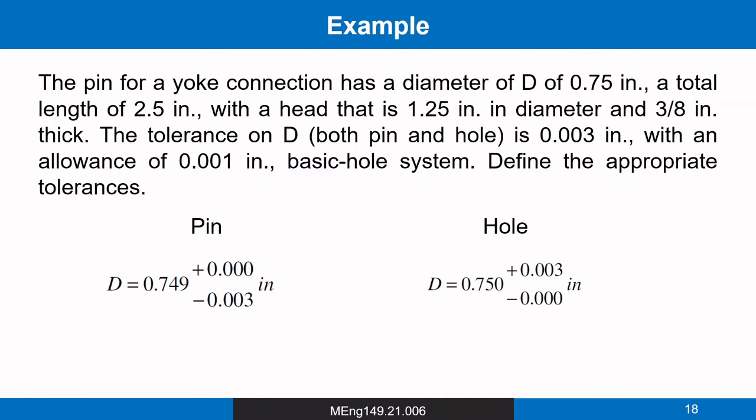So obviously, it is imperative that the pin is made this way, di ba? We cannot enlarge it so that it can be inserted in the hole. We are given a tolerance, so the application of this given tolerance of 0.003 is to subtract it from the size of the pin.